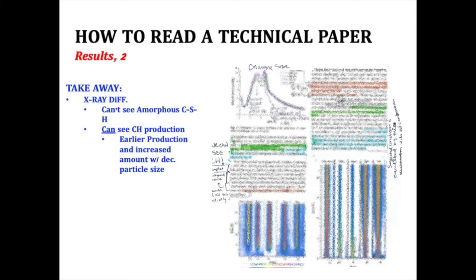calcium hydroxide, that Portlandite. Through their research, they looked at it through a more qualifiable method. They found that there was an earlier rate of calcium hydroxide production, and at an earlier rate there was more of this calcium hydroxide production, and this was within a 24-hour period, if memory serves me correctly, or 12-hour period. It also shows that there is a higher degree of calcium silicate hydrate production because the two are synonymous.